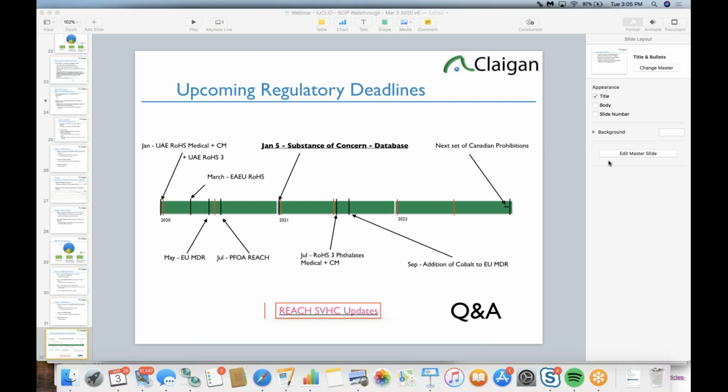A coating is a chemical until it's coated on. So you don't calculate the weight of an SVHC until after it's been applied, at the point where it no longer requires a safety data sheet. And they can go very metaphysical about really small things. Say for a resistor, in theory, you put coating on after coating, and at what time is it an article? We just say the resistor. Each layer in the resistor was a chemical until it made the resistor. So any SVHC in a coating, or in a layer in the resistor, is measured over the weight of the resistor.